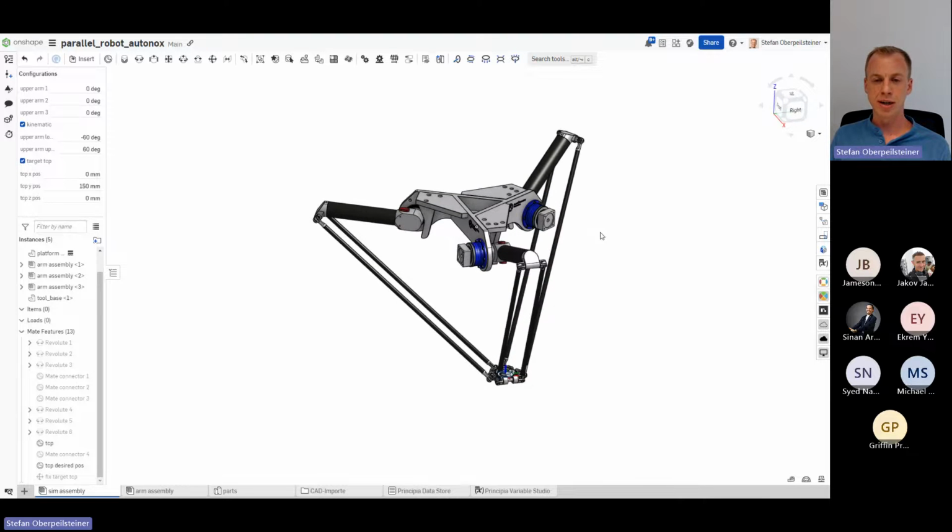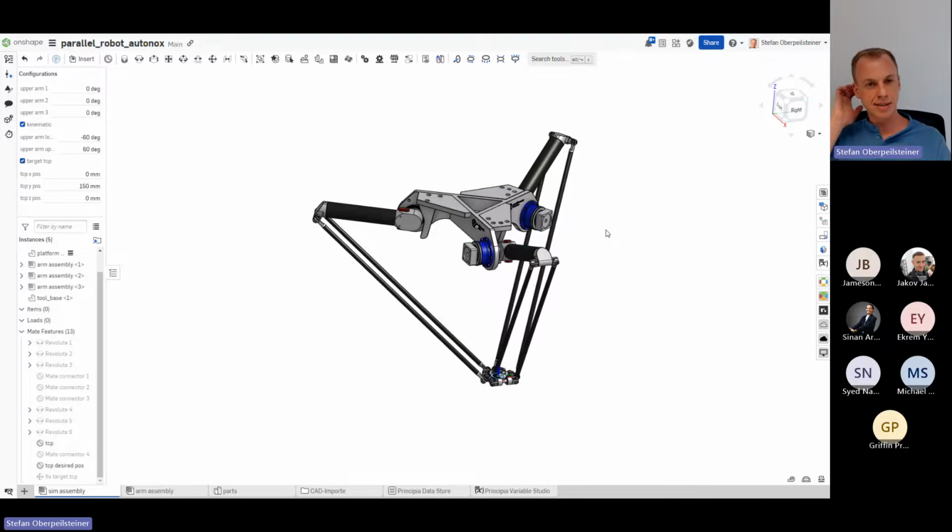And once I've done this, I can start with, of course, finite element modeling. That's the thing I won't show today because it would take some time. Just as information, this was done within Abaqus and then exported to a substructure, as I said. But nothing more than exporting the geometry shell from the CAD tool, then importing this meshing, and then generating the substructure. Good. And when this is done, one can jump into the Principia app.